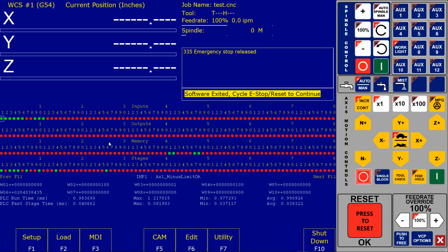All right, so now we can see that output 6 has been defined to OT6, and we can also see that input 16 has been defined to switch 16. Now I am going to flip a switch, input 16, and you can see that the output is turning on and off dependent on the state of input 16, which is exactly what we wanted. I don't know if you can hear it, but you can hear the relay clicking on that all-in-one DC.